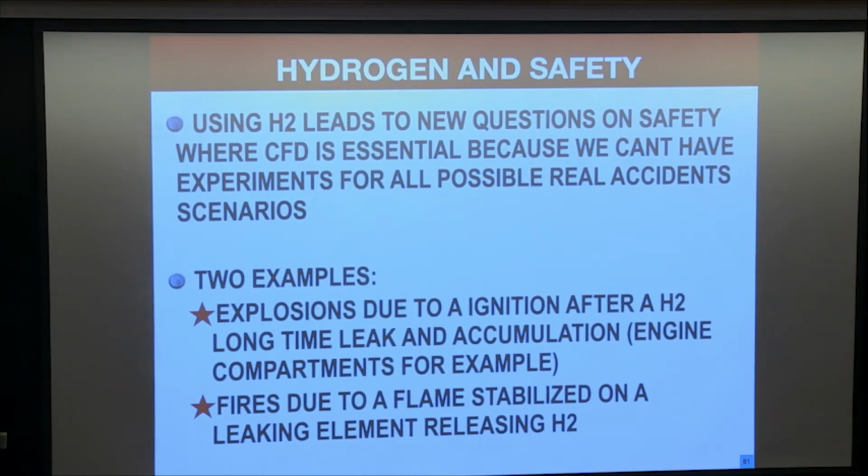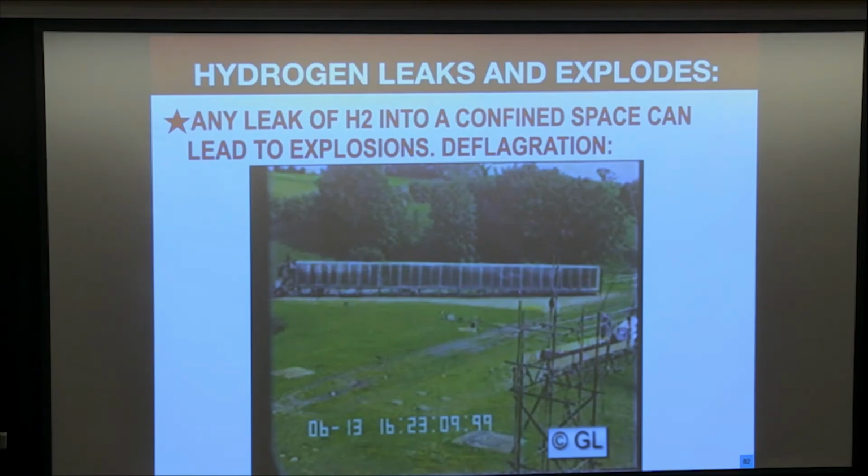It's not clear. I want to mention two types of problems with H2. The first one is you have a leak and it does not ignite, but it accumulates. If it accumulates long enough, at some point it will ignite, but that's going to be an explosion. The other scenario is that you have a leak, a hole somewhere, and right away there's a flame on it. And this flame is just sitting there. Well, we will see in a second, it's sitting there, but if you are around, you may have a problem. So you've already seen that.